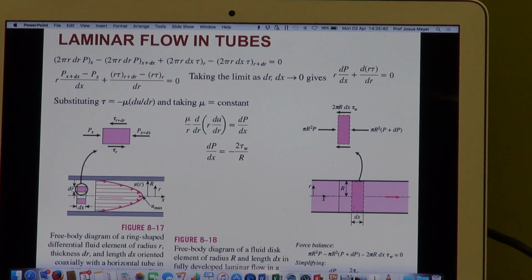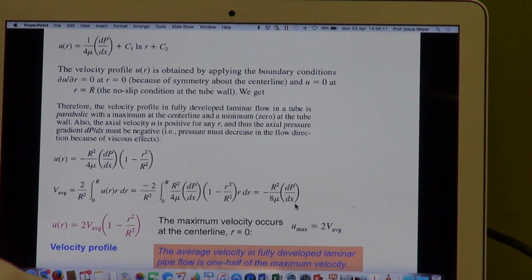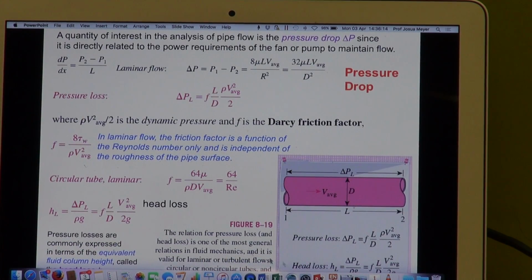Laminar flowing tubes is the next part, and what is important to realize is now that from fluid mechanics, for laminar flow, I've showed to you, or we have showed to you, the velocity distribution. The velocity distribution gives us the pressure drop. Also, from the previous 2 analyses, we can now actually derive the temperature distributions, and we can do an energy balance around a control volume. And then firstly, before we get to that, just